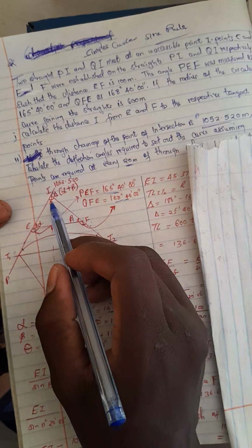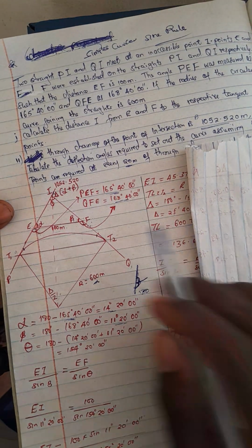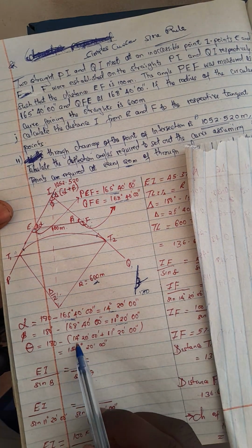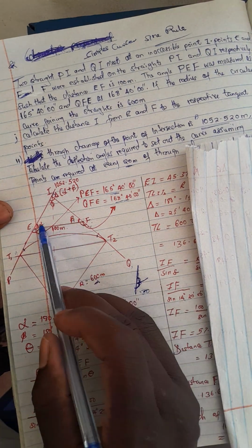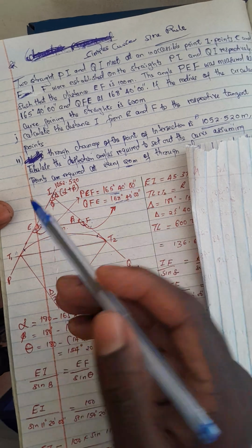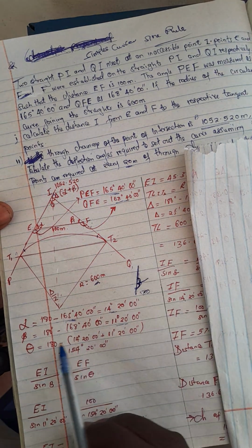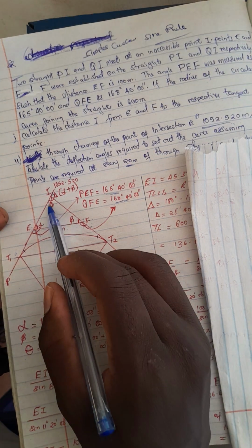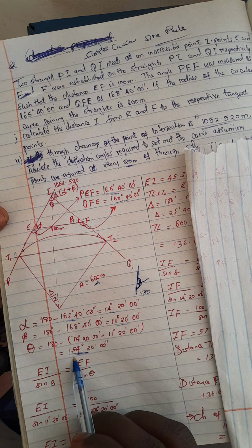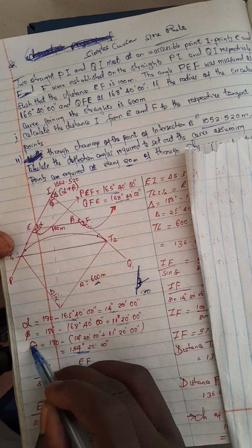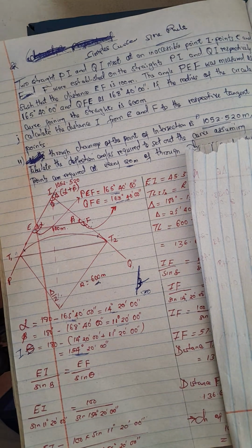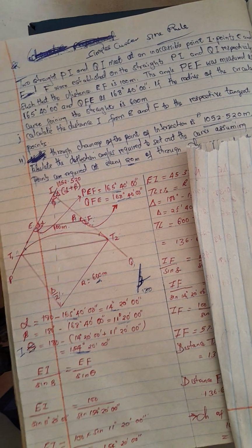Now I'm getting the angle of intersection here. How can you get that? Just add this one, which will be the deflection angle, minus 180. Minus 180 will get the intersection angle to be 154. This angle now, it is 154. So this one is the intersection angle. Okay. Yes.